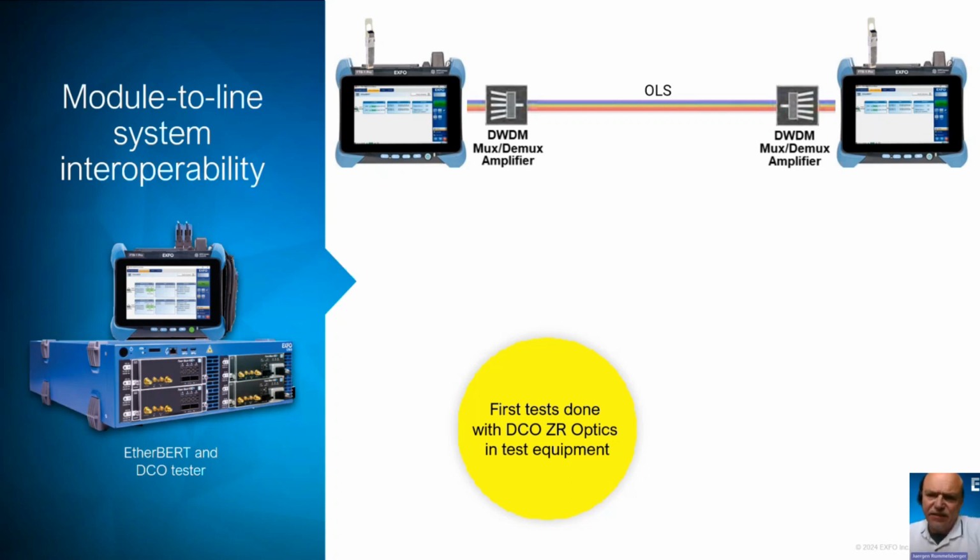This repeats the host-to-module verification in this way. But to finish the further setup, the same procedure then has to be applied to the second tester for having an end-to-end testing, meaning that once configured, the BER can then be determined on both ends, and the assessment of the signal integrity can be made here.